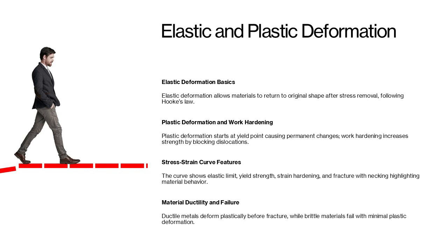The stress-strain curve illustrates these behaviors, showing elastic limits, yield strength, and strain hardening regions. True stress-strain analysis becomes important near fracture, especially during necking. Understanding these concepts is crucial for predicting material performance under load, designing components to avoid failure, and selecting appropriate forming processes.